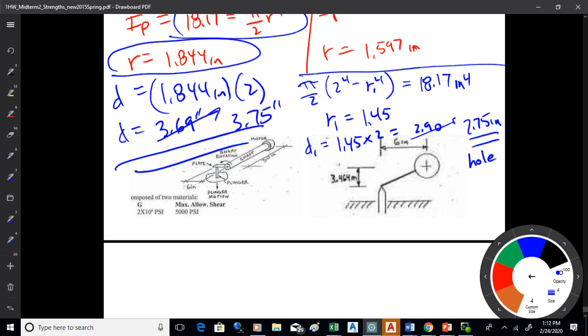And the hollow shaft uses the material more efficiently, you know, so those types of shapes that put the area out a long way from the axis, they're cheaper usually, or use less material. You do have to consider the fabrication costs and what you're doing. So are we doing all right with that? Just trying to go over that one.